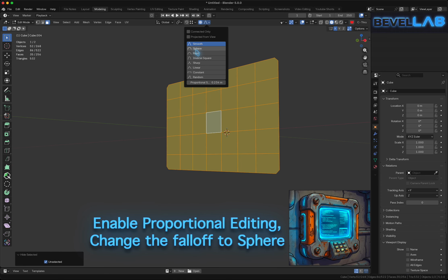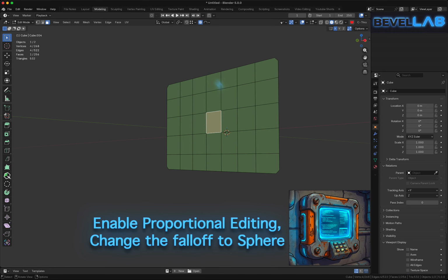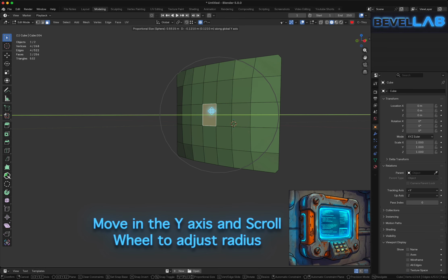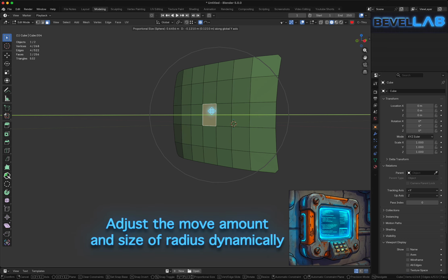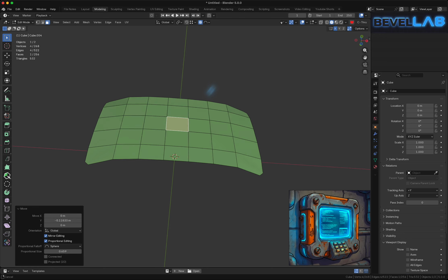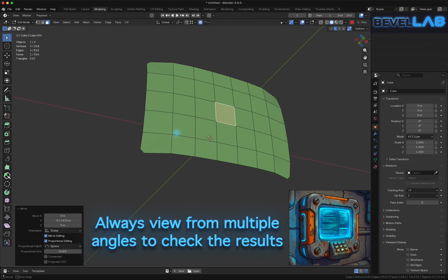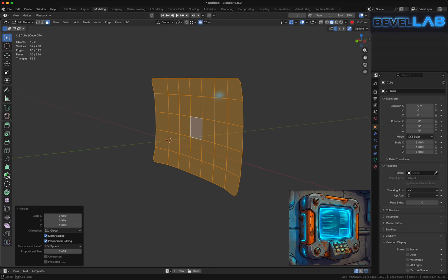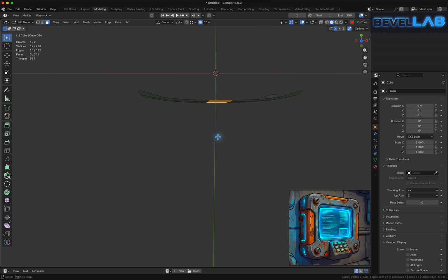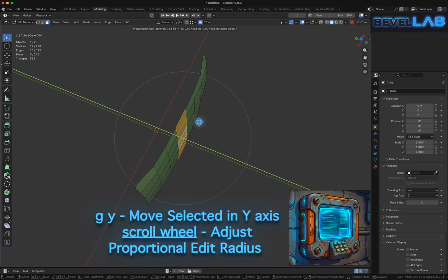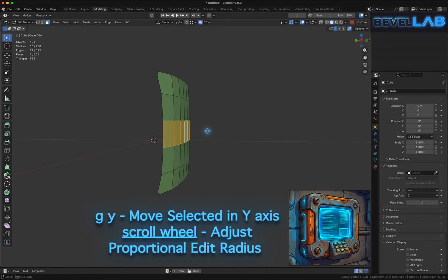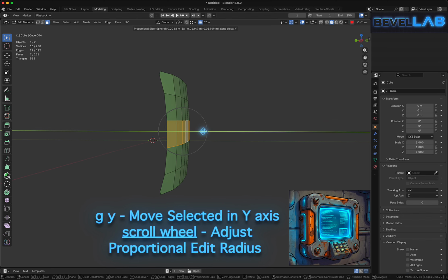We're going to use that neat proportional edit function again so you can get a different perspective on how it works. Remember, you can use the scroll wheel to adjust the effect fall off radius before you commit. If you did commit and you regret that commitment, why not change the terms and conditions before you do anything else by using the pop-up in the lower left corner? Or continue to tweak and scale and mess around until you are a little bit less dissatisfied with your results, like I am doing here. Can your human eyes even see the difference?